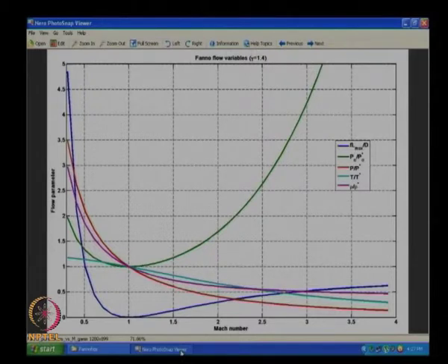Okay. What this means is, if I have a choice between my M1, the inlet Mach number of my tube, to be subsonic or supersonic, if I choose to go for very long lengths, it is better off if I go with subsonic flow than supersonic flow. Is it logical? If we think about whether it is logical, I will simply say that it is a flow through a duct with friction.